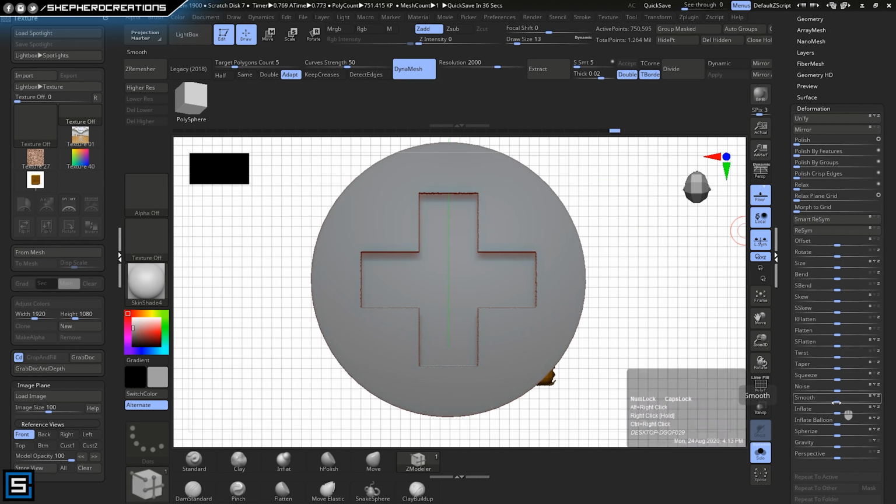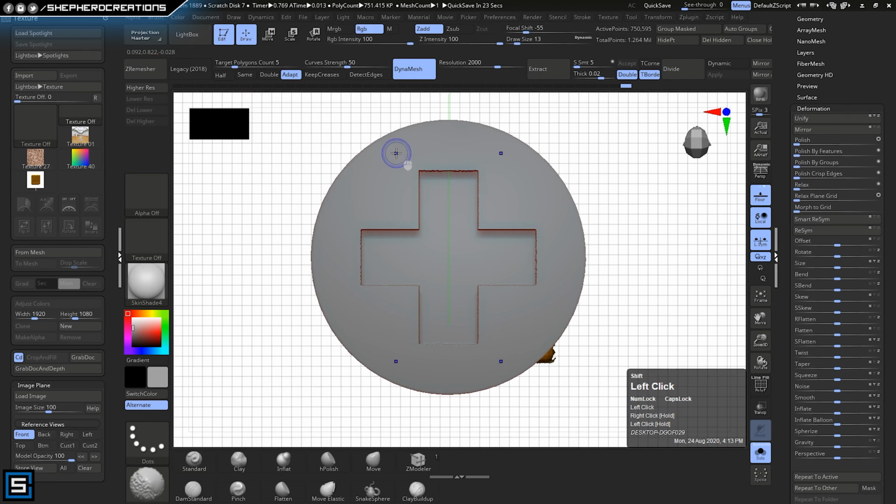I tend to do that with Fusion360 in a lot of ways, but I decided to use the deformation tab and use the negative inflate. And mind you, I use the negative inflate, not inflate bubble, because the inflate bubble tends to distort the inflation. I wanted the selection to be a lot more crisp and clean.